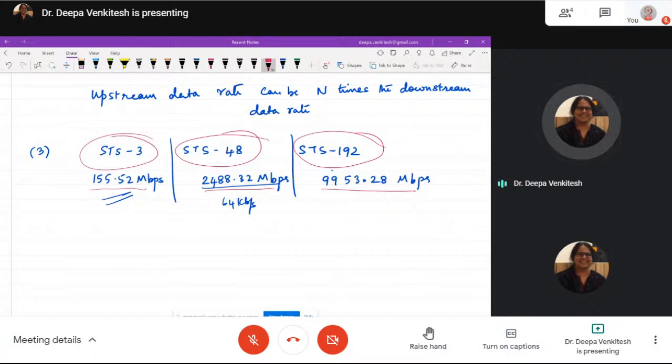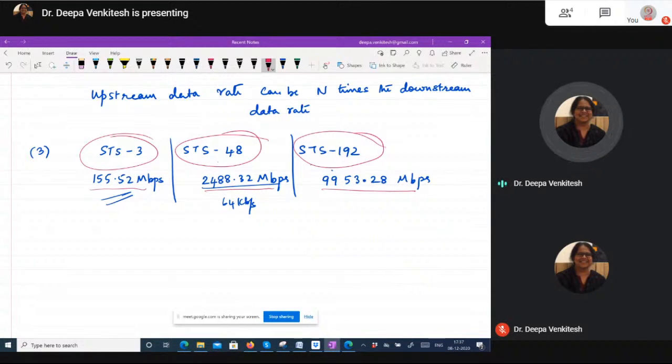The next question is also trivial. We are now moving from voice channels to video channels. So from 64 kbps, we move to 20 Mbps. In our very first lecture, or in the first week, we learned why the voice channel requires 64 kbps. How did that number come about? So you can now correlate with that and say, in the case of a video channel, how many can be transported in each of these cases. So depending on how many video channels you want to transmit, you can now think of designing the system to deliver those many voice channels and video channels.